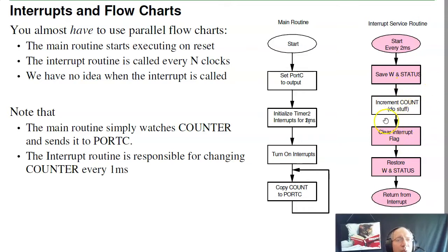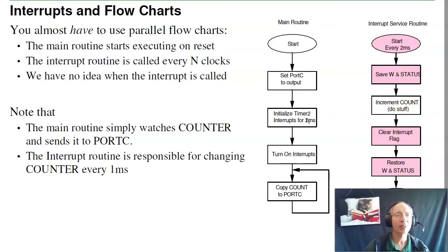Also notice the style for the interrupt. There is no looping, there's nothing else going on, it's get in, get out quickly. That's because the next interrupt could be happening at any time. I do not want to do any looping inside the interrupts. I just want to execute the code very quickly, then return from interrupt.